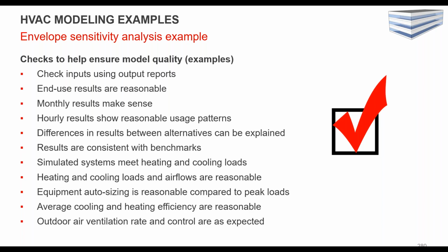I see a couple questions. Jose asked, are occupancy sensors used for DCV? Increasingly, yes, we're seeing occupancy sensors being used for DCV, where the same occupancy sensor is controlling your lighting, your VAV box minimum, and your outside air damper. So it can be that. I would say in terms of modeling, you're really going to be using whatever the software does. So you might be creating a schedule that mimics your occupancy, or some alternative where they're calculating a CO2 generation rate.